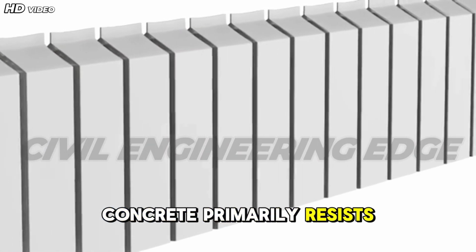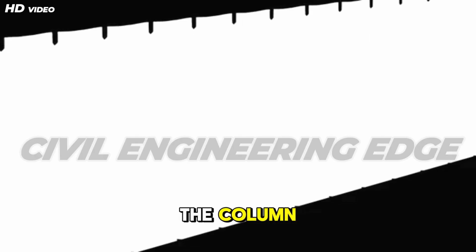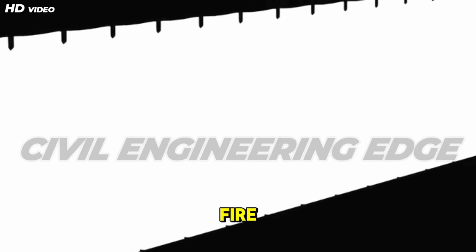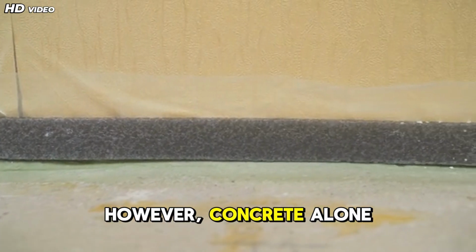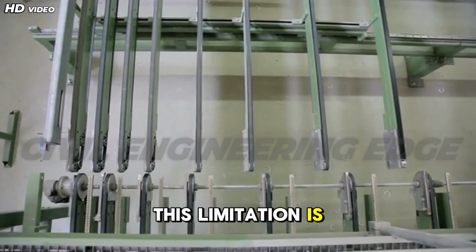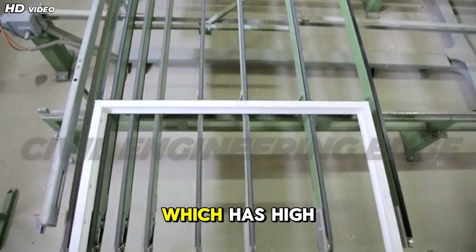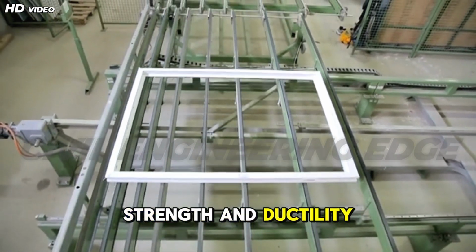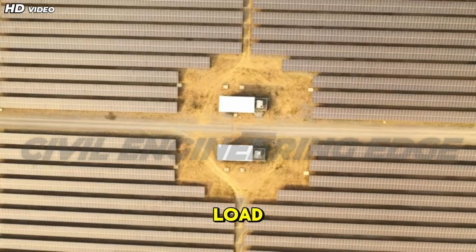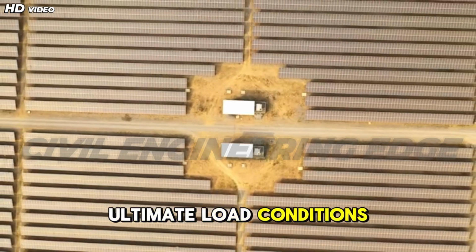Concrete primarily resists compressive stresses and provides stiffness and mass to the column. It also protects embedded steel reinforcement from corrosion and fire. However, concrete alone is weak in tension and prone to cracking. This limitation is overcome by introducing steel reinforcement, which has high tensile strength and ductility. The interaction between concrete and steel ensures load sharing and strain compatibility under service and ultimate load conditions.